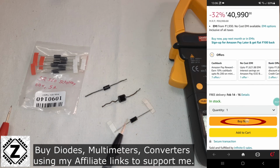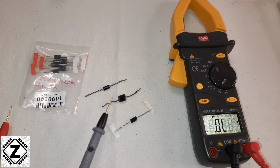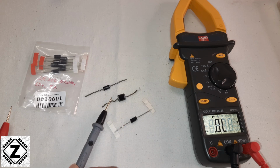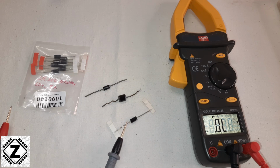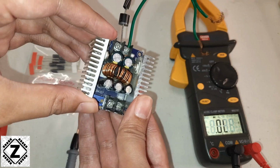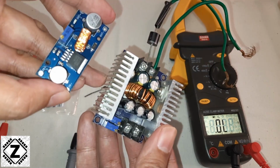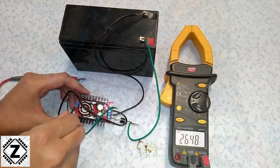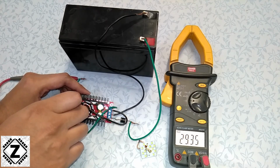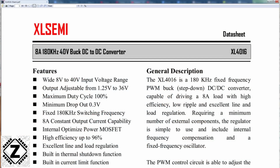There are some other advantages to having a Schottky diode. The first advantage that we talked about is that it has much lower wattage loss or power loss compared to a silicon rectifier diode. The other advantage is that it supports high switching frequency. For example, I have a bunch of circuits over here. These are known as DC to DC buck converters. And the chips in these buck converters allow switching up to 180 kilohertz. That is very fast switching.